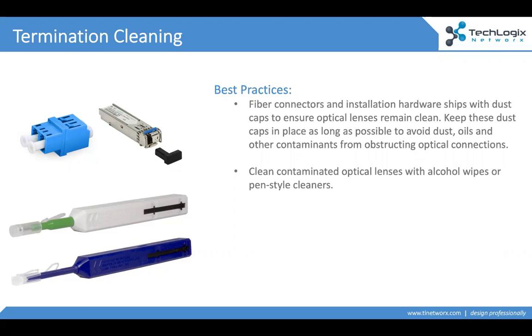Now, one other best practice that you should get in the habit of: anything that's fiber optic comes with dust caps. Whether it's the electronics, the connectors, or the cables, keep those dust caps in place as long as possible. They will help you avoid contaminants getting into your system. As soon as you remove those, anything floating around in the air can start to get on those optical lenses. So keep those dust caps in place, and clean the connections before you connect stuff. Certainly if you're working on a retrofit, pay attention to cleanliness, and to optimizing and cleaning those older connections that have been installed for quite some time.